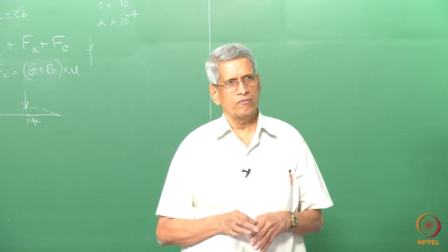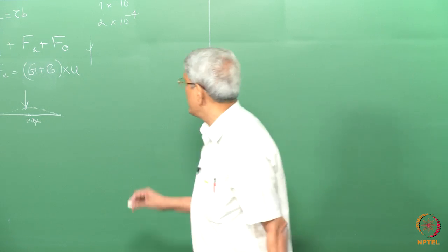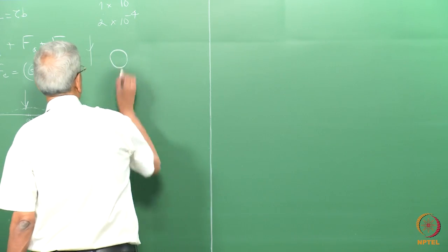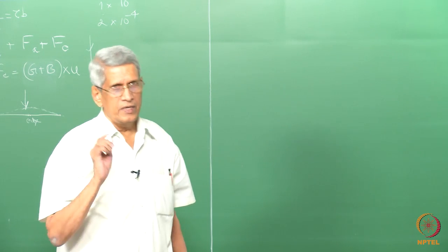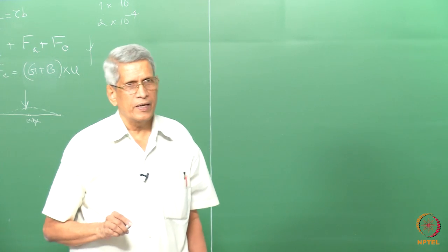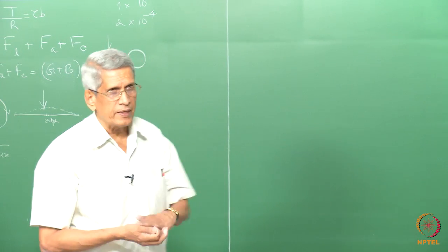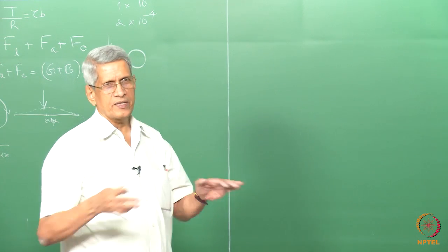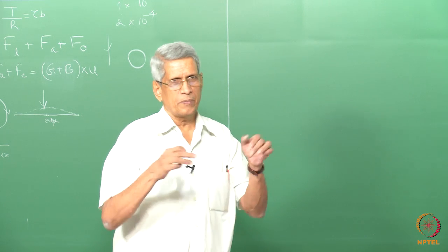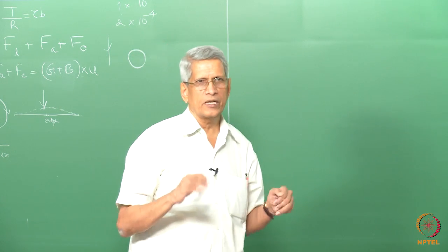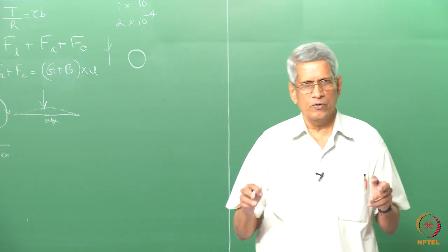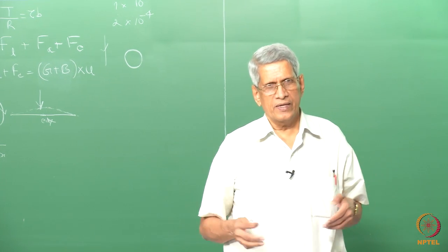Then we will see a lot of dislocation loops. These loops are essentially Frank loops. In FCC, on a close packed plane, if vacancies condense on a close packed plane, that means atoms are removed from that layer. This will be equivalent to generating a Frank dislocation, right?